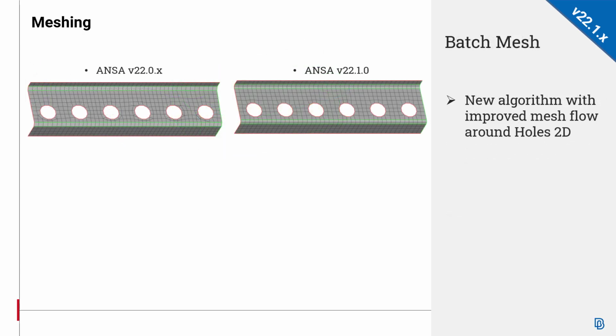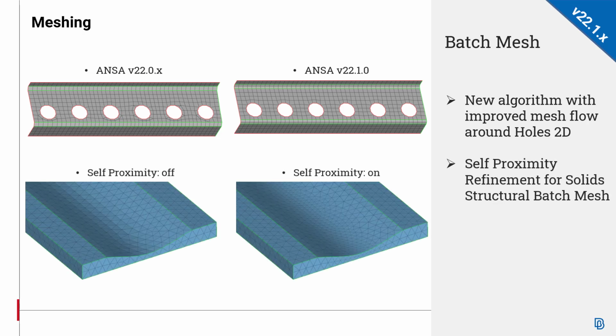With respect to batch mesh, we have greatly improved the algorithm for mesh creation around 2D holes, while for solid structural batch mesh, we added a new option for self-proximity mesh refinement in areas where quality criteria violation is expected.